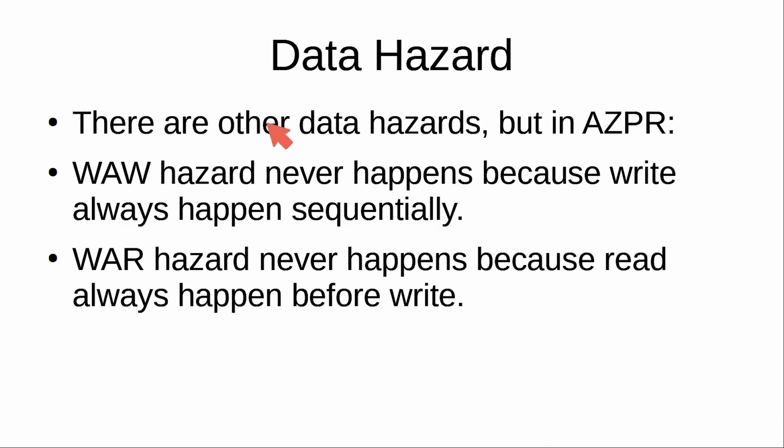There are also other data hazards, but in our processor, the write after write hazard never happens because write operations always happen sequentially. As for the write after read hazard, it never happens in our processor because read always happens before the write operation.